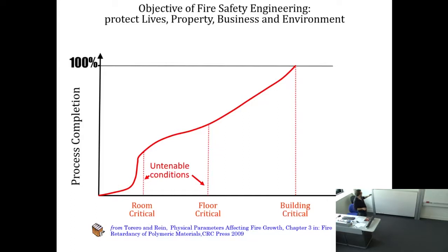This is a plot where you see time, things are happening, the events are evolving, and this is how complete the different processes are. In red is the fire. The fire has an ignition, that's where everything started. At the beginning it goes slowly, then starts to accelerate. Then comes something we're going to discuss later, called flashover, when the fire engulfs the whole of the room of origin. It cannot literally be bigger than the size it has reached, conserving the loss without breaching the laws of nature. And then it might go to different rooms or different stories. So it breaches the room of origin.